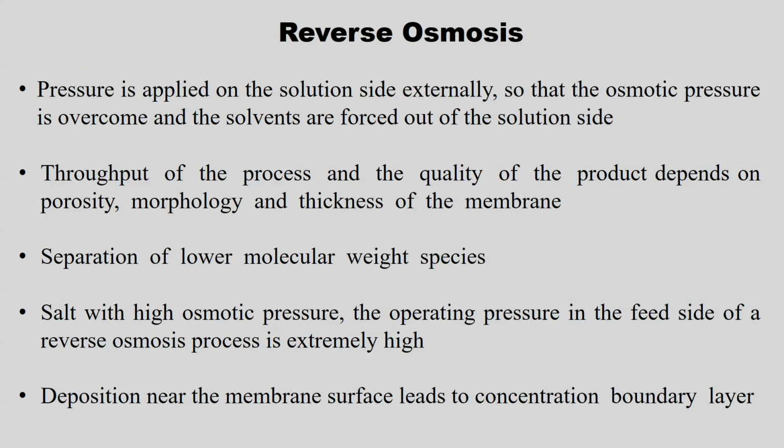Then another basic operation. This also we are going to see in detail in the advanced membrane separation processes. Here we will just see the basic definitions and what happens in reverse osmosis. The pressure is applied on the solution side externally, so that the osmotic pressure is overcome and the solvents are forced out of the solution side.